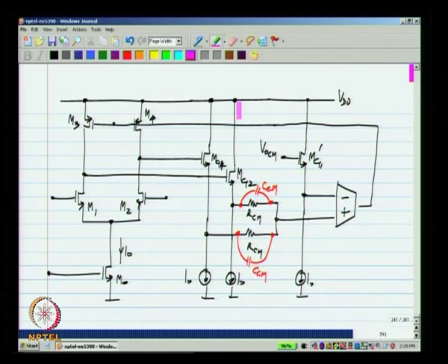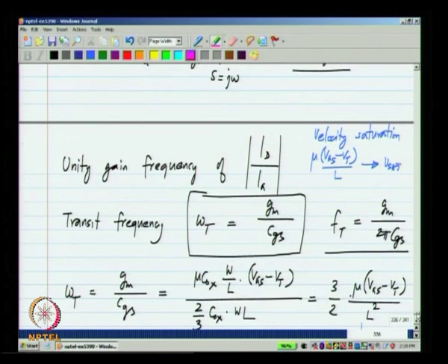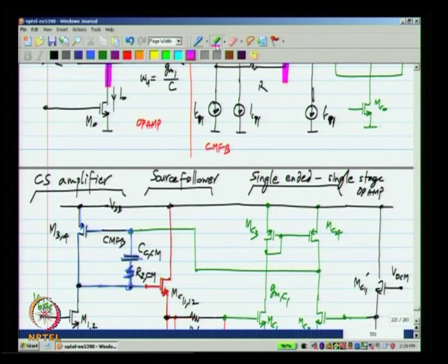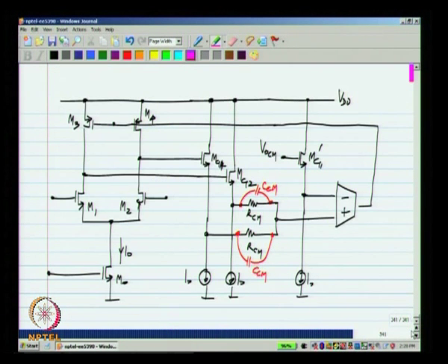In the common mode half circuit, it appears between the gate of M34 and the drain. Okay. So, in the fully differential circuit, it will appear between the gate of M3 and M4 and each of the drains. Okay. Something like this. And finally, the actual load of the op amp will be here, C and C.